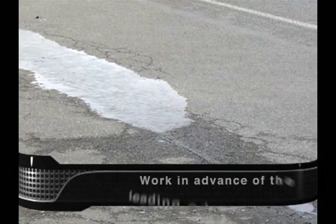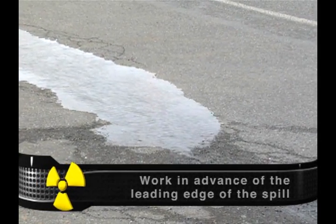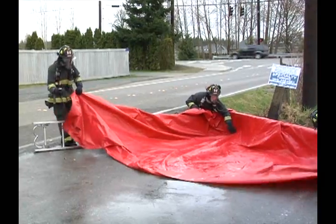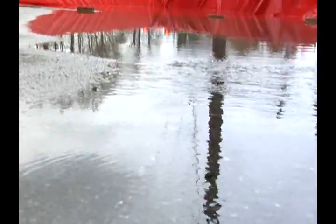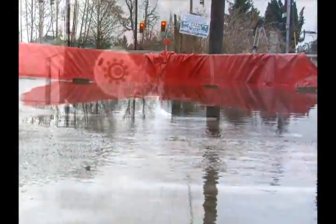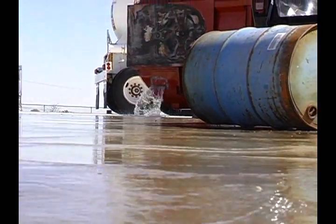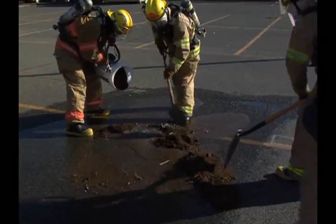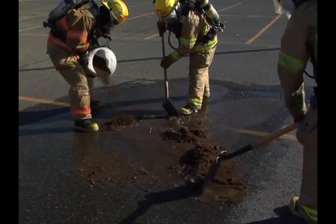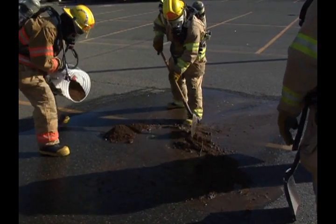Second, always perform confinement measures in advance of the leading edge of the spill. Build a diversion dike or a retaining basin in the area where the spilled product is going, not where it is now. With most flowing products, if you attempt spill control operations behind the leading edge of the spill, you will become heavily contaminated, and the product will be far beyond your confinement area by the time you finish.